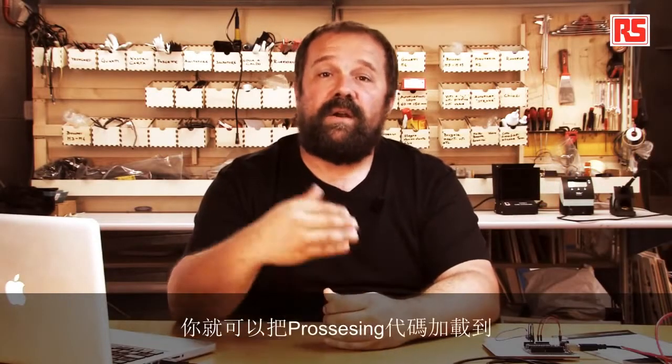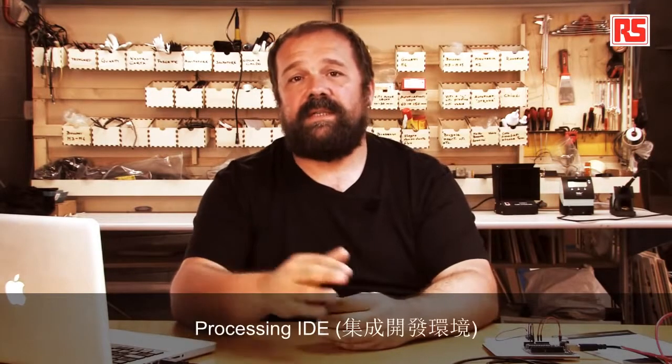After that, you can load the Processing code into the Processing IDE, and you can load the Arduino code into the Arduino IDE, and then transfer the program onto the Arduino board. And after the code is loaded, you will see that the TX LED will start to blink, signaling that the Arduino is sending data. So you can open the serial monitor, see the data scroll on the screen. After you see that, the Arduino part of the work is done. You can close the serial monitor.